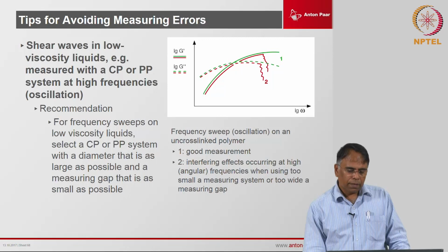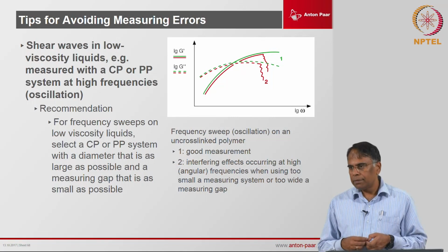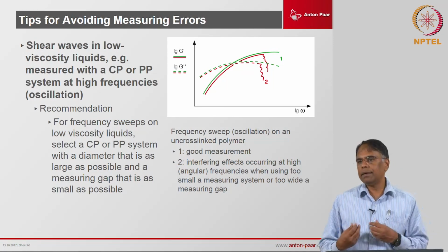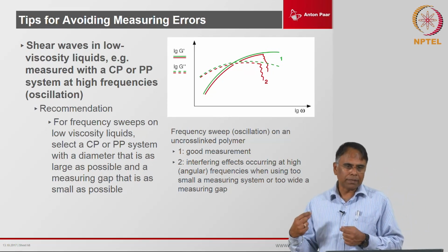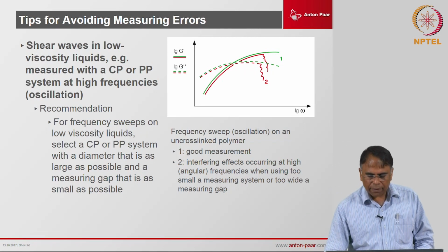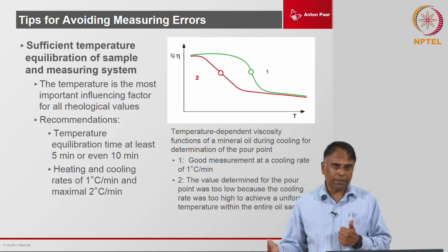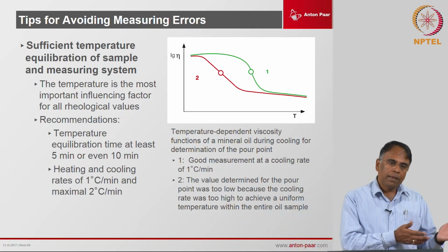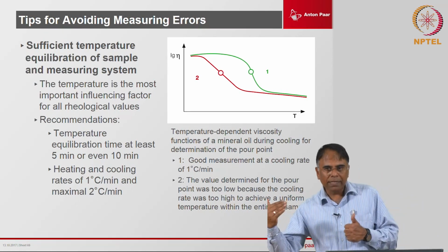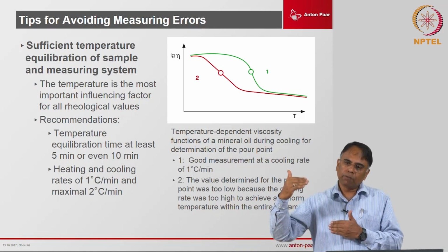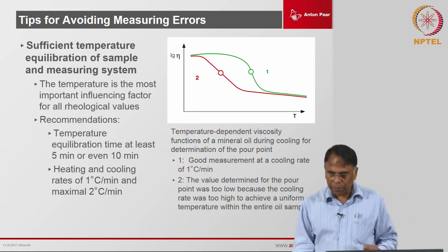For bars also you will have the same. So, the bars itself will also expand or contract, okay, based on the temperature, and we can actually use a very small normal force to control this effect, and the change in length also can be measured as a function of this effect. So, with the normal force control, you see this gap changing as a function of the force, okay. To maintain that force, you can actually measure your gap as a function of temperature also.